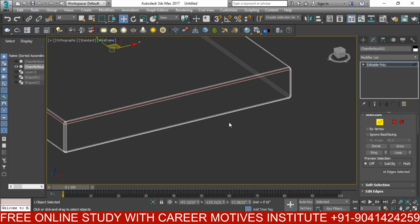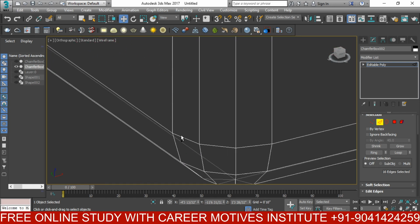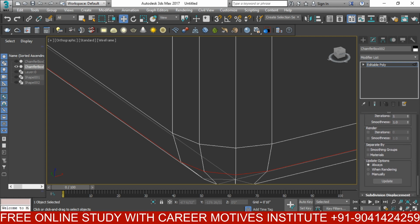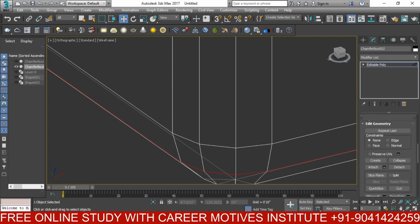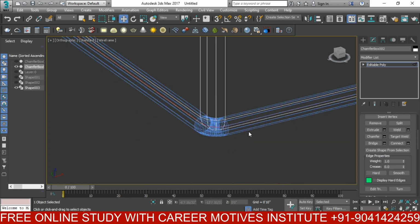Again I'm selecting the bottom portion like this and loop, and I'm going to select the option, and the option is create shape from selection.